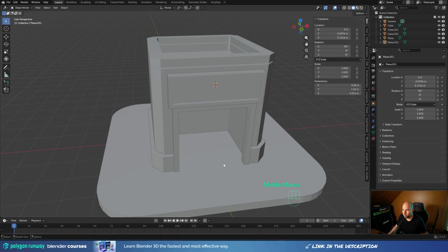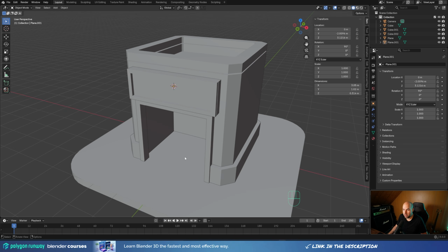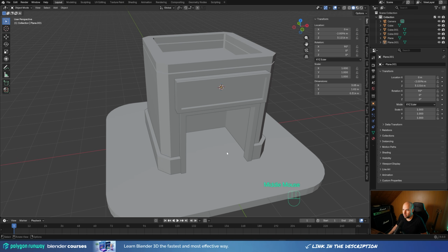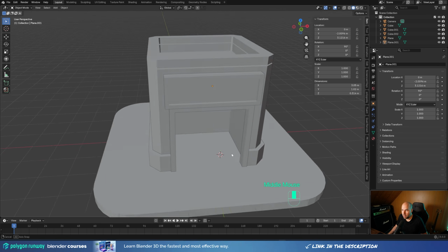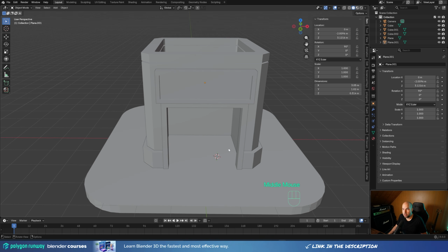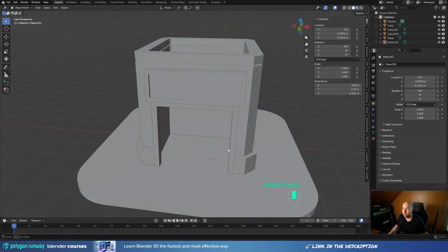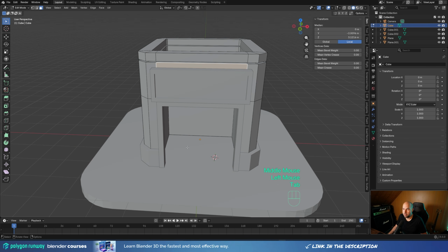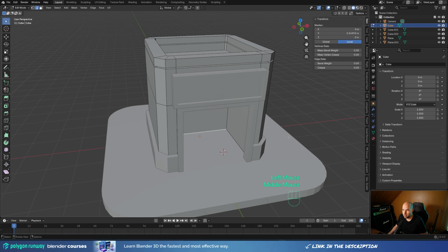And let's add a little bit more detail here in the back. I want a countertop there, and you could easily just go and hold Shift and right click to place cursor somewhere and try to position your newly created plane or a cube or something. But again, I like to reuse the geometry, already existing geometry with already existing proportions. So we can now select the building, tab into the edit mode, and I can clearly see that this edge is exactly what I want here. So press 2 for edge select, select this one, and we can just press Shift D, then Y, and move it right here. And additionally, we can press P and separate it into a new object.